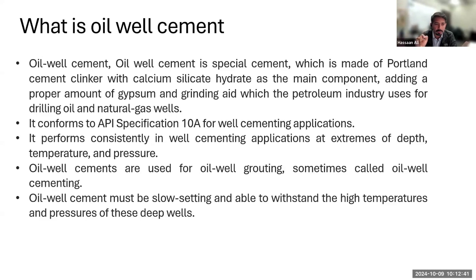It has to conform to a certain API. API is the American Petroleum Institute specification, which is called 10A. It has to conform to that. So the composition of the cement, its properties, and specifications are all governed by the API 10A. And it needs to perform consistently in well cementing applications at extreme depths, temperatures, and pressures.